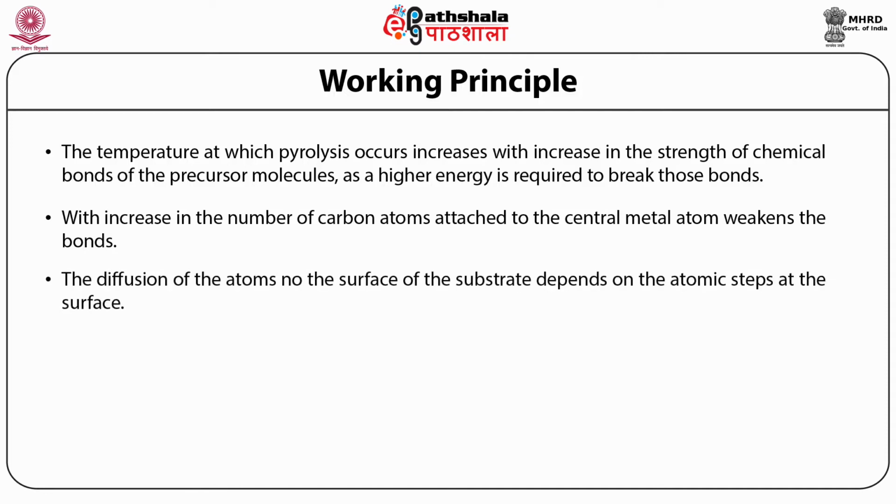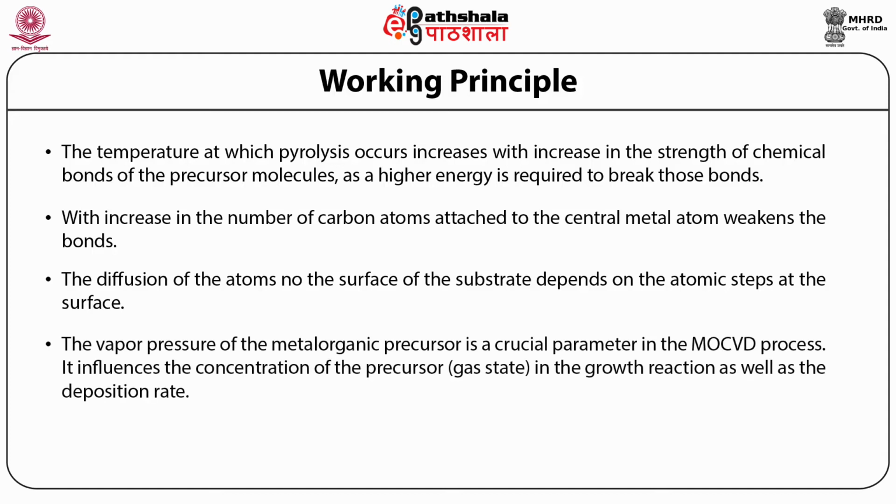The diffusion of the atoms on the surface of the substrate depends on the atomic steps at the surface. The vapor pressure of the metal organic precursor is a crucial parameter in the MOCVD process. It influences the concentration of the precursor, that is in gaseous state, in the growth reaction as well as the deposition rate.